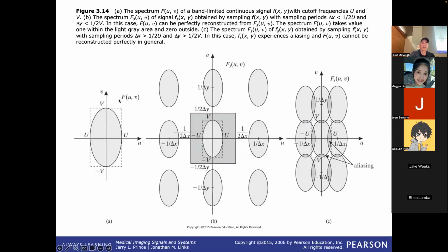In 2 dimensions, same thing. This is the Fourier space, the Fourier transform of a continuous function fxy. And then here's the domain over which I have frequency values for that function, right? So we say it's band limited. It doesn't have any higher frequencies than we see in this ellipse. We can set a sampling grid such that when we look at sampling that function and taking the Fourier transform of those samples, we are separated from all of these replicants. And so this is a clean representation of that band limited function. It's inside that box.